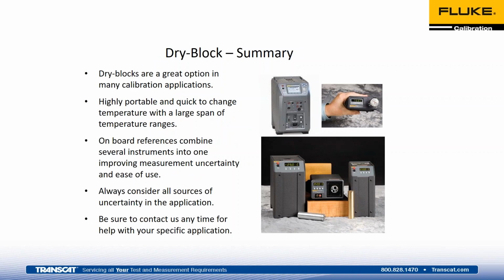So just in closing, dry wells are a great option for a quick heat source. There's a lot of temperature range to choose from. And if you need it, you can get the ones with the built-in references. And a lot of different insert options as well as range options.